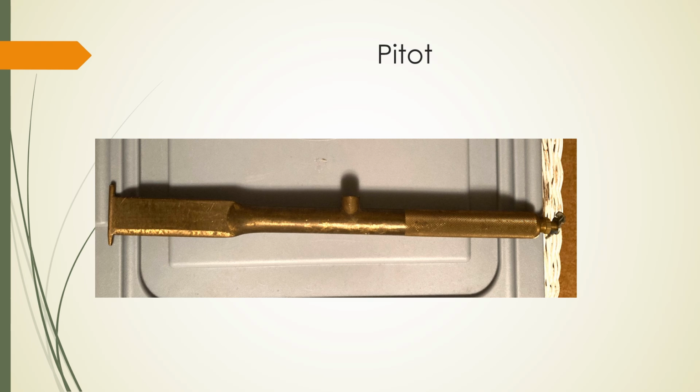Not all pitot tubes are created equal. I use this one because it's easy to use for lower pressures, but it's hard to cut in and get the right pressure for really high flows. You need to be able to keep the unit stable in the flow. There really is a certain art to getting the right number. It's got to be in the middle of the flow, and I think 1/2 the distance from the opening, the size of the opening.